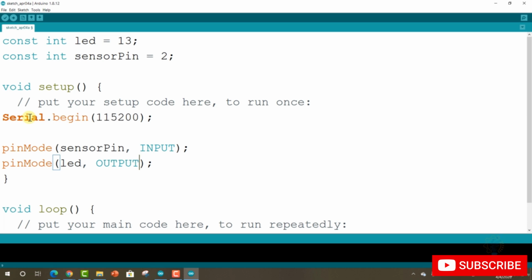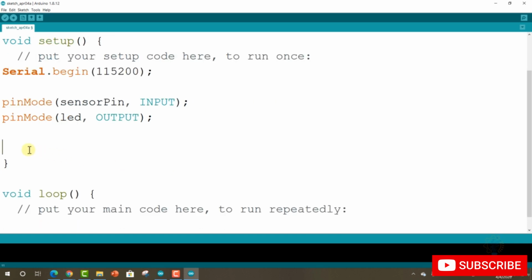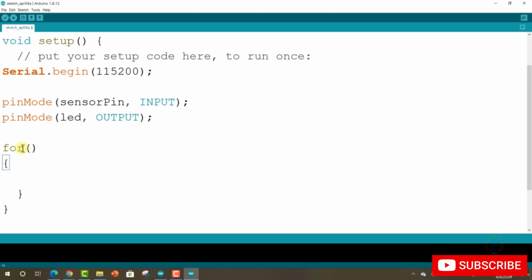Now we need to wait 1 minute for the sensor to calibrate. So to calibrate, again, we need to wait 60 seconds. And in order to make sure that we are still in the waiting process, let's create a for loop that will turn the LED on and off for 60 seconds. So let's start, for. Now the code inside the for loop will be the following.